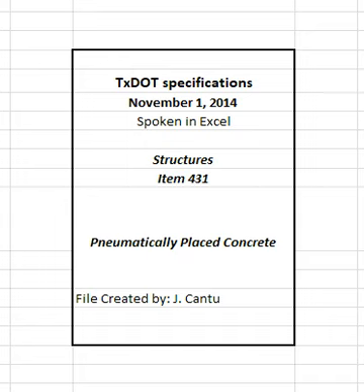Use 3/8 inches diameter rods placed through these holes to secure the reinforcing fabric. Hold the reinforcing fabric at least 3/4 inches out from the surface of the steel member. Lap adjacent fabric sheets at least 6 inches and tie together at a spacing of no more than 12 inches.